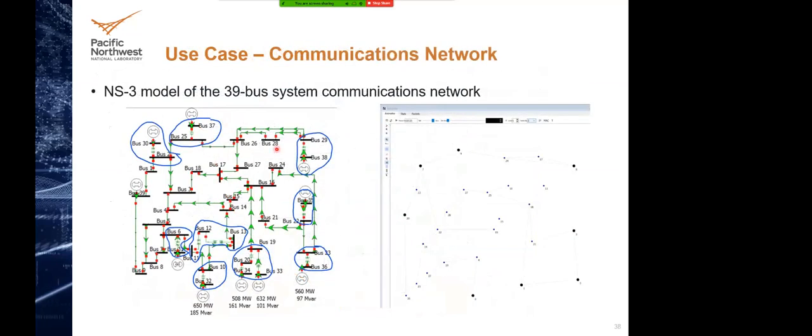And also on the communication side, we've built the communication network for this 39-bus system, where we treat buses connected directly with a transformer as one substation, which corresponds to one communication node in the network.